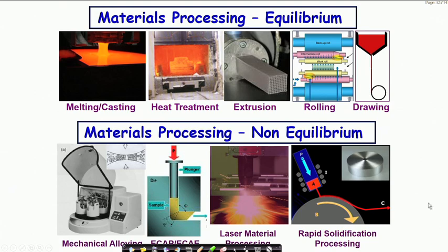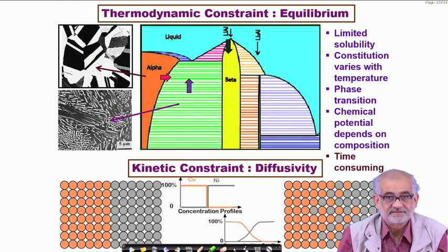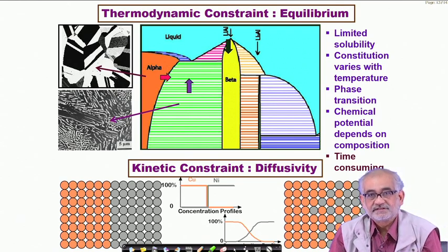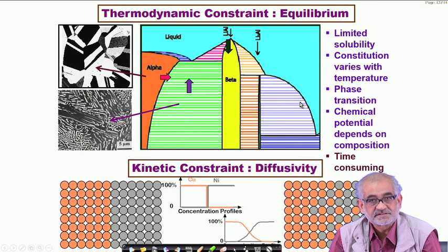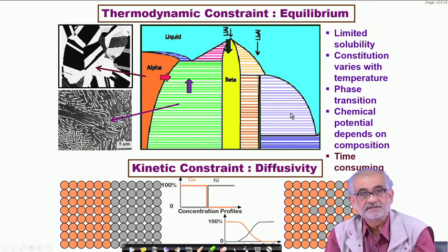This solid that we form instantly may not be of the exact shape, size and geometry that we want, but this is the beginning. Now, when we do this processing, we also have to be aware of two important aspects. One is the so-called thermodynamic aspect related to the equilibrium. This two-dimensional pictorial description is the so-called thermodynamic phase diagram, where the x-axis describes the composition of a binary system and the y-axis refers to the temperature, assuming that in a condensed system like this, pressure has very little influence.